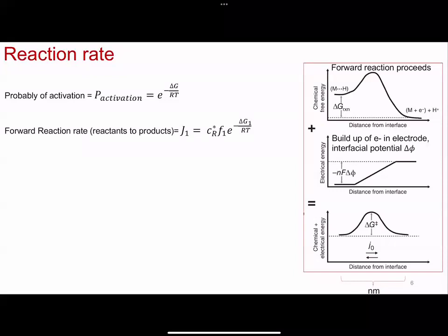So then the fuel cell reaction gets split into, well, if it can be split, it'll go forward. So the hydrogen gets split into protons. That's a forward reaction in this particular case for hydrogen oxidation. But the reverse can also happen. If the protons see each other enough, they collide, and the reverse reaction will happen. So obviously you want to split the hydrogen, form protons, and have them migrate. You want to minimize the reverse reaction, right?